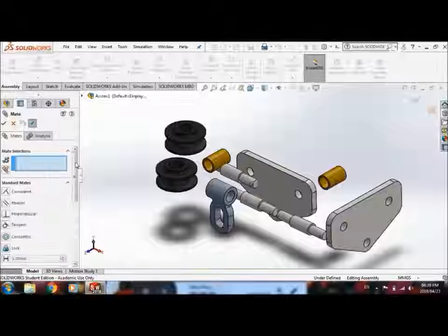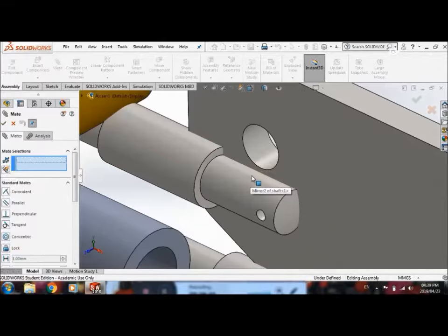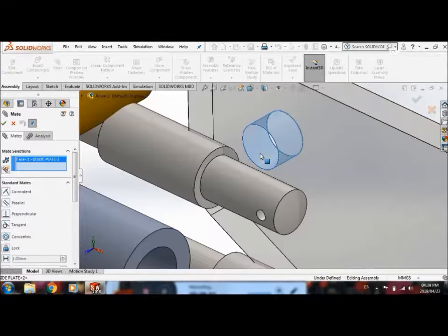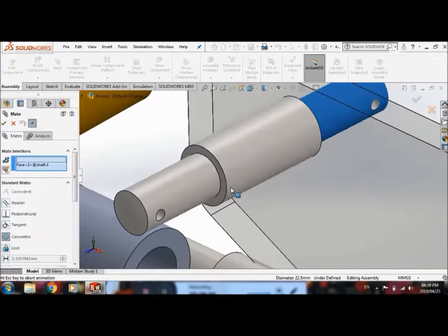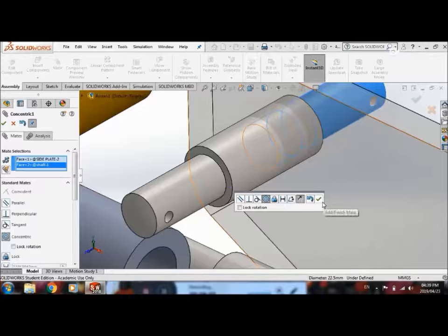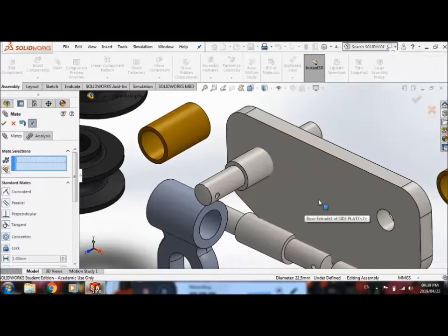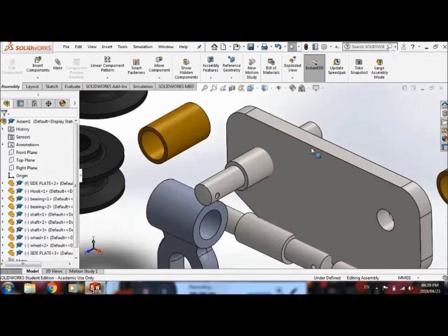Now the nice thing with SolidWorks is it is kind of clever in understanding what it thinks you want it to do. So you don't have to tell it must be coincident or concentric. If you click on 2 circular things like that hole, click, and this shaft, click, then it automatically puts them concentric. Right, so what it did there is it put the one inside the other one. It won't automatically detect that components are interfering.